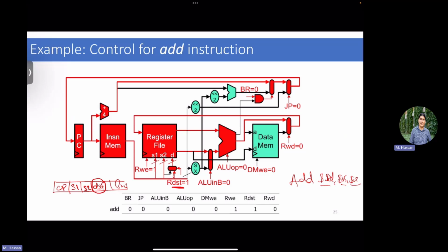So in that case, for the register file destination from the memory, the mux here should just pick the normal ALU path, so this selection line should be 0. I don't have branches, I don't have jumps in an add, so simply every selection here should be 0 to pick up the normal activated path of program counter plus 4. Good. So going back through these 3, 6, 8 signals, you end up simply with your R destination is 1, register file write enable is 1, everything else is 0.